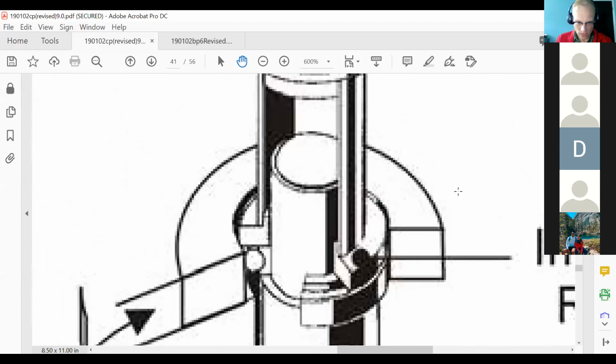Now, this one, a bit of a special circumstance. So what they're saying here is this shaft and this bore housing here, both are in place. And this bearing is driven or interference fit on both of them. This tool sits on the inner and outer race. It doesn't sit on one or the other. It's driving on the full surface.